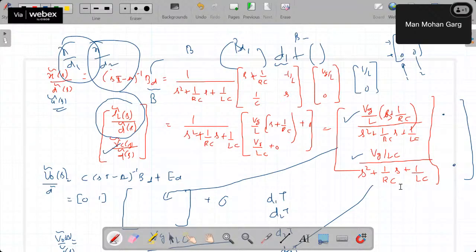If 3 circuits are there, then for the first circuit you write the state space model and multiply it with 10 microsecond, plus the second circuit multiplied with 15 microsecond, then the third one with 25 microsecond. Like that we can do averaging. But if we are saying modes are different but the circuit remains the same, then I think we cannot say different modes. Then the number of modes will be reduced only.